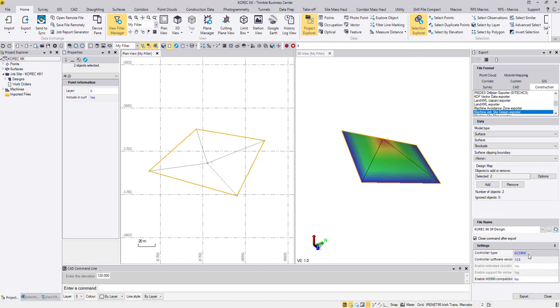And then the most important bit is the GCS version. So you pick PCS there, CAT AccuGrade. But the version, what I usually do is drop it down to 10.7, so everyone can use it. Doesn't matter if you have MS980s, 990s, any version from CB430, 450, 460 up along, it lets you open it up. But if you know the specific version, if you open up the control box, it'll tell you what version. So it goes all the way up to version 13. So you accept that. It says, are you using 990s? Yes or no. And then you click export, and that's how you do your GCS900. That'll create an SVD and SVL file.